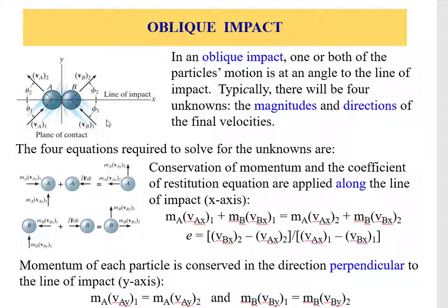First of all, you establish the line of impact by connecting the centers. Now that's going to give you the line of impact. The impact plane is perpendicular, so it's in Y. Second, you establish your coordinate system, so you make your coordinate system along the line of impact. The first thing you will do is apply the conservation of momentum about the line of impact.